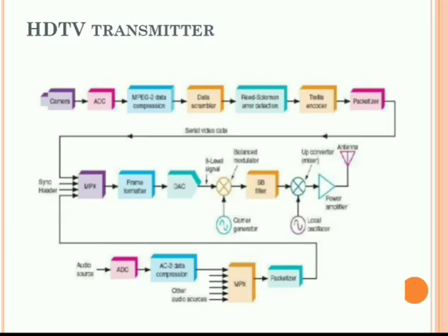For example, one channel could be used for a second language transmission or closed captioning. Each audio channel is sampled at a 48 kHz rate, ensuring that audio signals up to about 24 kilohertz are accurately captured and then transmitted. This is how it is flexible to permit the different systems in that particular